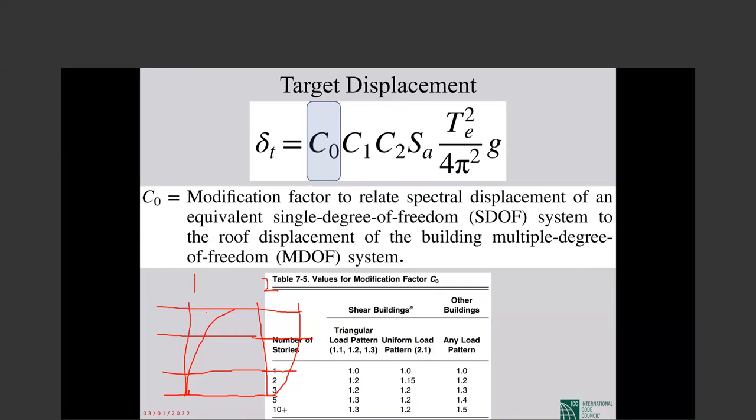But this one bay frame mainly goes through axial deformation in those two columns that it has. One is in tension, one in compression, but generally the building's form is bending. So when we name it as bending or shear, we don't talk about the element type of behavior.